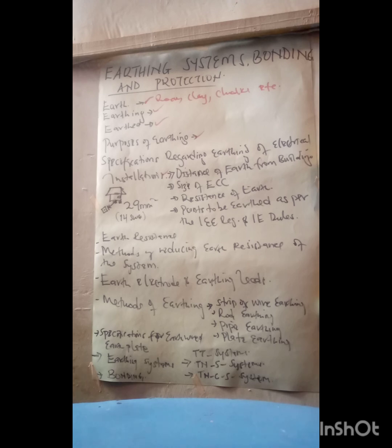The loop earth wires used shall not be less than 2.9 mm square, that is 14 SWG, or half of the size of the sub-circuit conductors. And lastly, the earthing electrode shall always be placed in vertical position inside the earth pit so that it may be in contact with all the